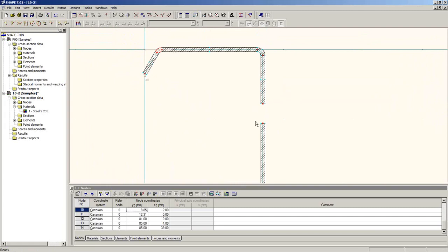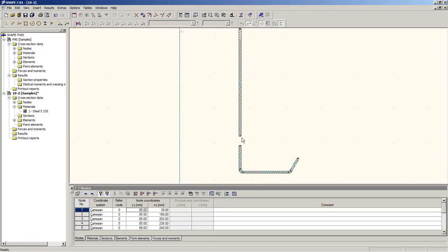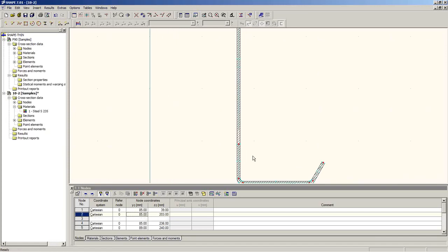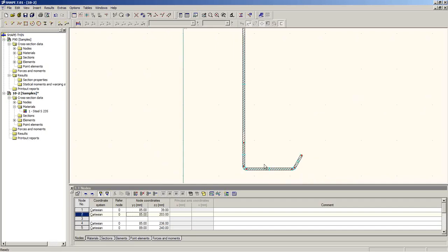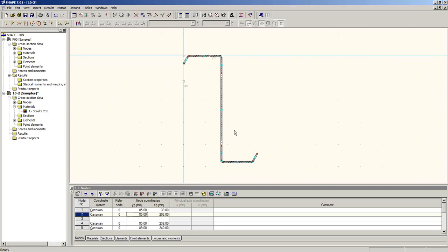Here in this model I had, there was an opening for bolts, and because I'm going to use this cross-section to model a three-dimensional or a 1D beam, but it's in 3 dimensions then, I don't want to have this opening along my beam, so I close it here because the bolt holes are typically only a local problem. So I can just click and drag the nodes to the next connecting node and it will automatically connect. Okay, my cross-section is then ready for analysis.